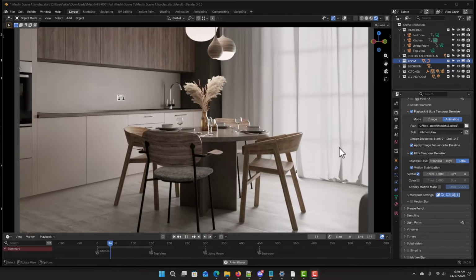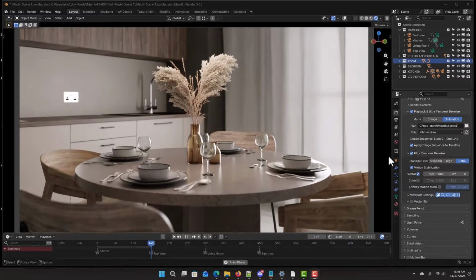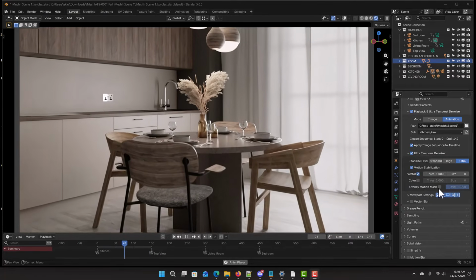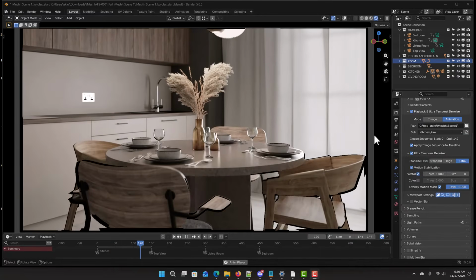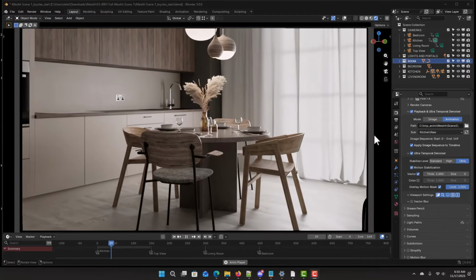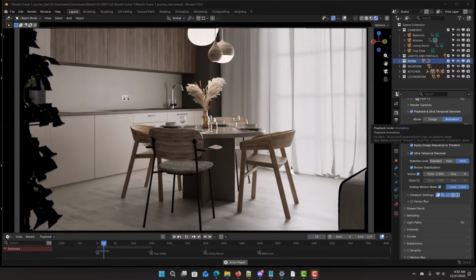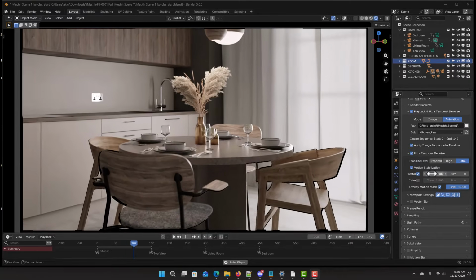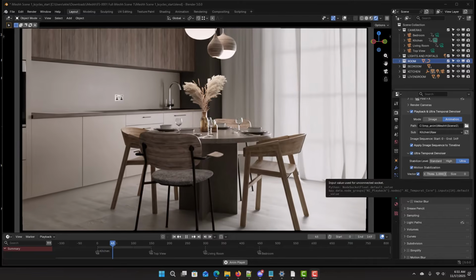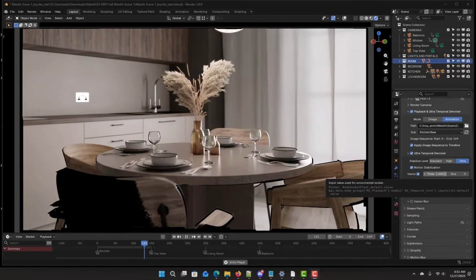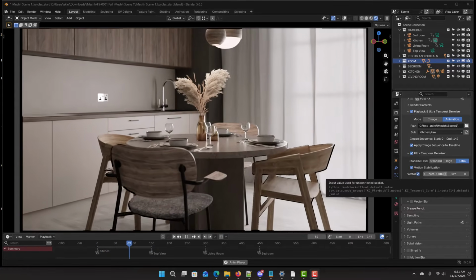To visualize how the motion vectors are reducing the ghosting and temporal artifacts, enable the overlay motion mask, and you'll see black outlines at the areas where there is no stabilization for the reduction of the ghosting artifacts. But those areas will flicker and do not have stabilization. The goal is to have the threshold as high as possible. Right now it's set to 1. The threshold should be as high as possible, which means less black mask for best stabilization and flicker removal, as long as the ghosting or temporal artifacts are kept to a minimum.